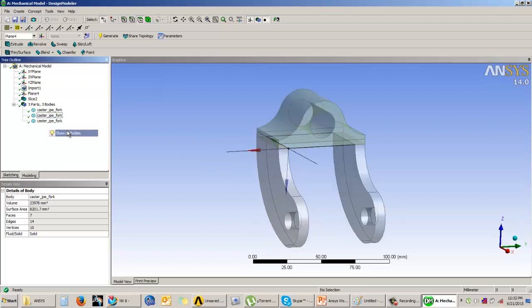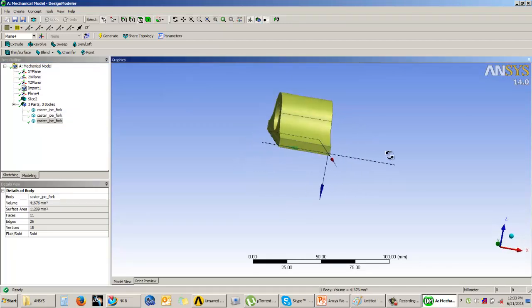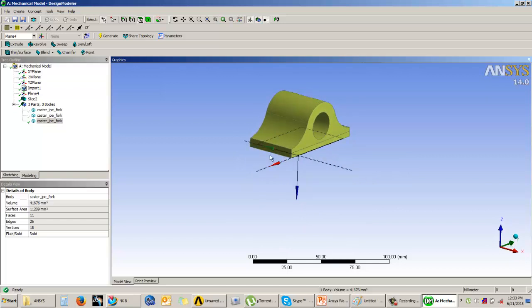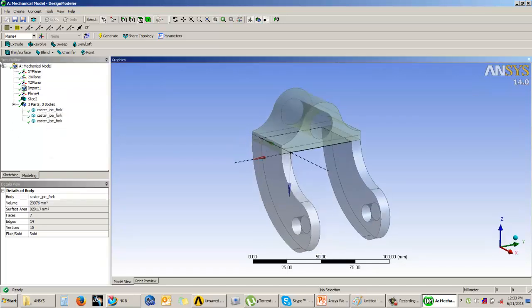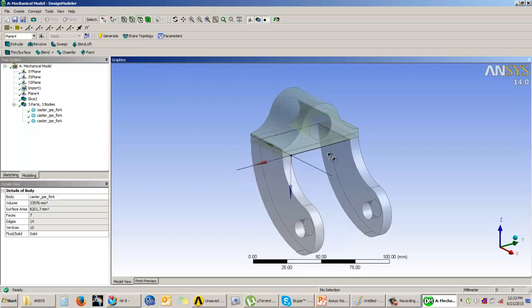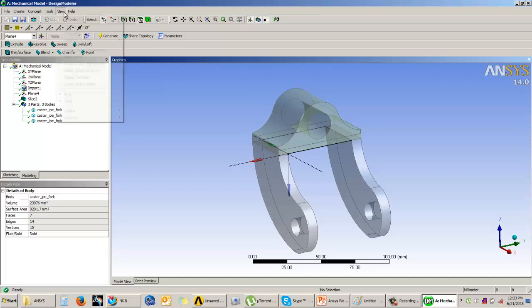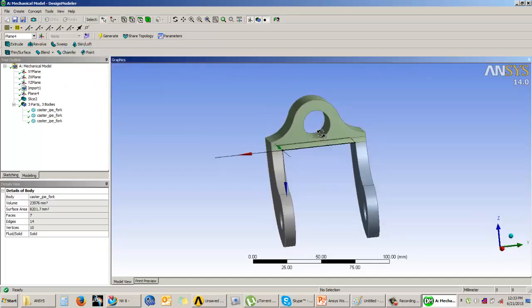Then again, if you look at this body over here, again this is simple extruded geometry. That means it is sweepable in this direction. So what we have got is, by using the slice tool, we have got 3 separate geometries. Okay, now they look transparent, so I will just switch off this frozen body transparency so that they look opaque to me.